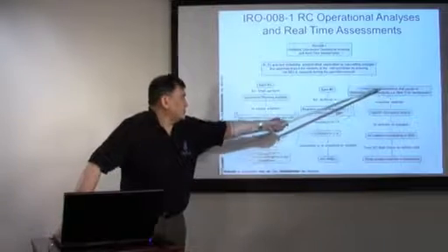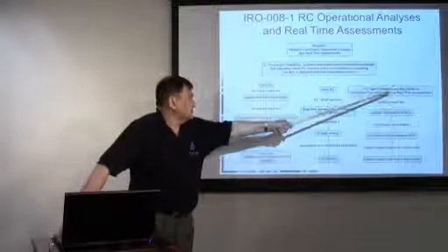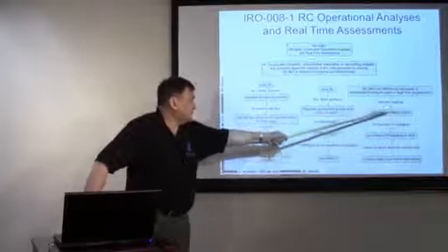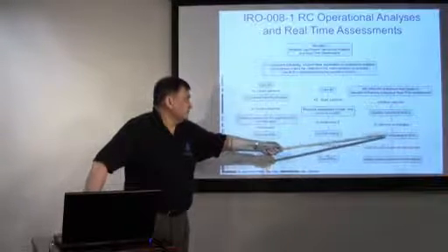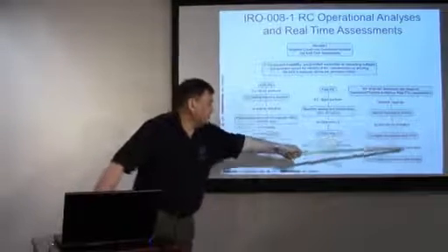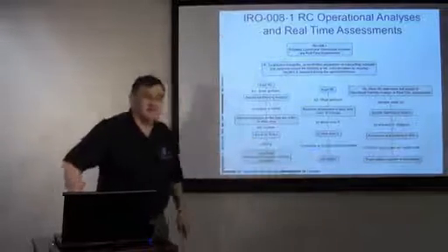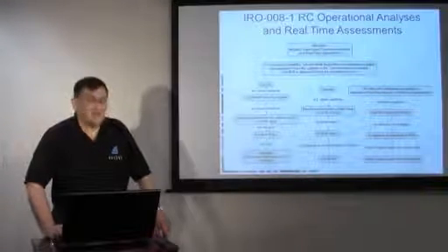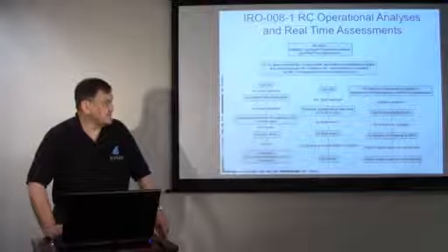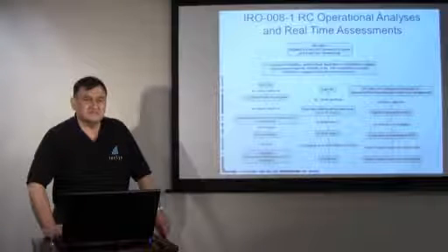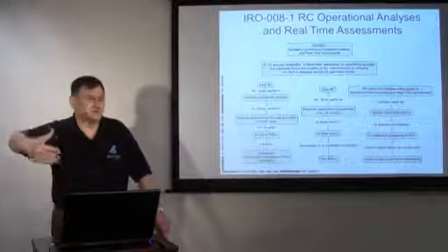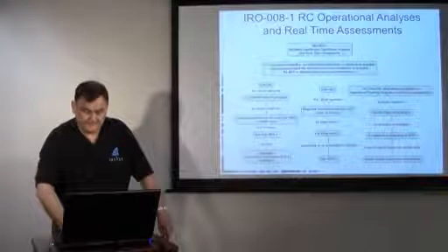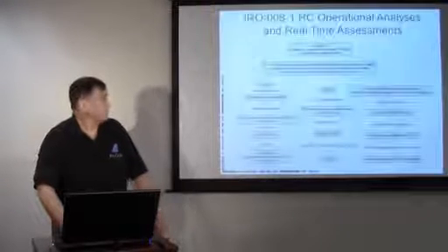And so when the RC determines that the operations planning or real-time assessment has a need for operating actions to prevent exceeding an IROL, it shall share the results for those members to take actions. This can be having a common set of displays, but typically this is phone conversations where the RC is calling you and saying, look, Joe, you've got a violation. You need to take some action on that.